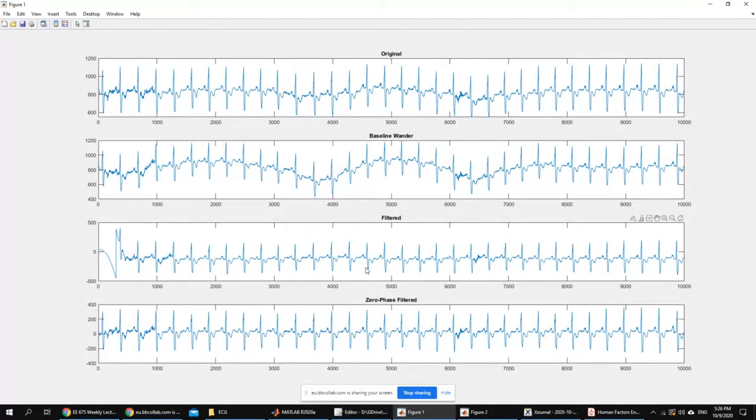Trying to match this to that is a tedious process, and I don't want you to get into it. So just use the zero-phase filter, and based on its error, you can conclude whether this filter is good or not. Compute the error from the zero-phase filtration, even though you might be using regular filtration in practice.